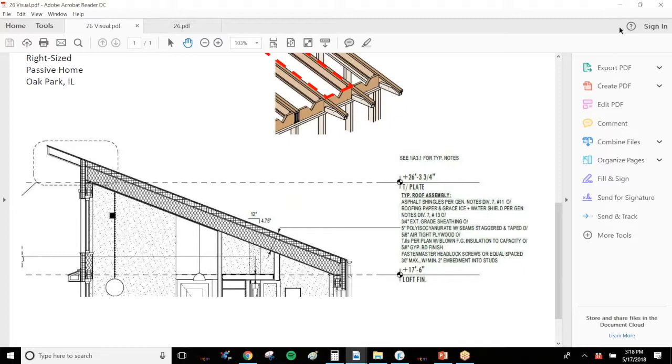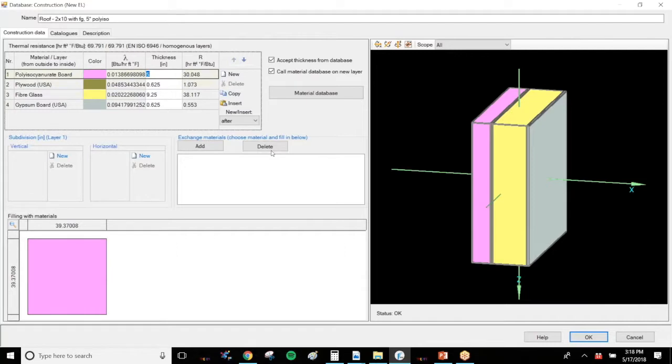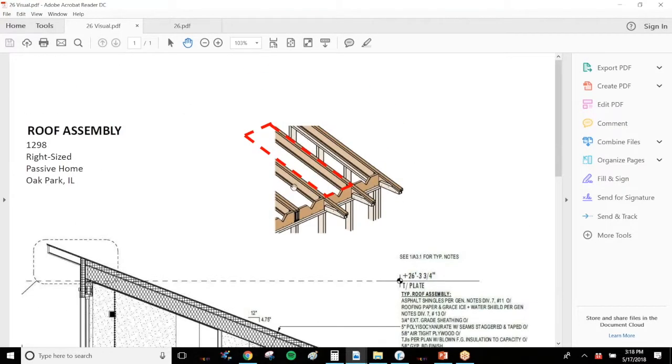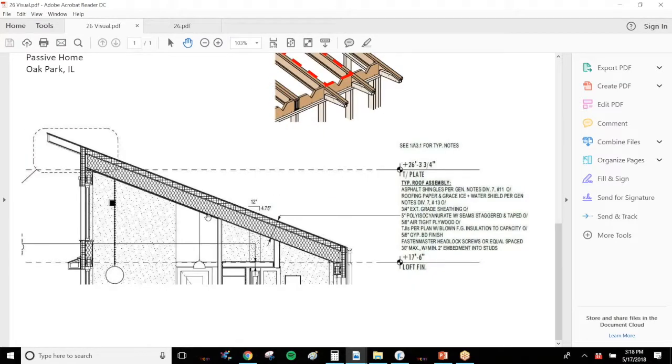Actually might be 30 inches. Okay. So we're going to say the roof, we're going to add framing every 2 feet, and it's going to be going in one direction. So if we look back at this, the framing is just going in this direction. So it doesn't actually matter what direction we cut the framing or we cut our portion in the other direction. So in this particular case, we could make it the whole dimension of this building if we're assuming framing is running one direction for every 2 feet, and then it's running the other direction, maybe at the top and the bottom. For our purposes, we're just going to add framing in the one dominant direction, the consistent direction.